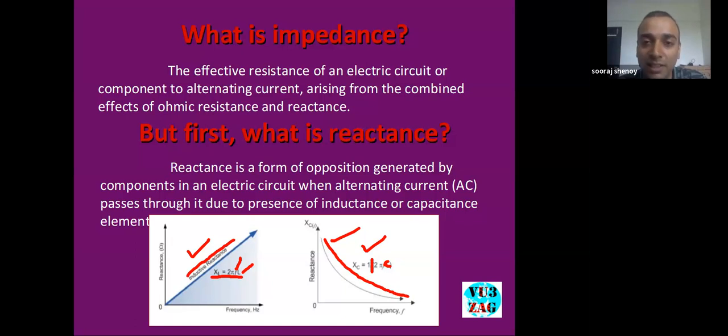As I mentioned, this is a QRP tuner and can work perfectly below 25 watts. For higher watts, the same design can be used, but the capacitor needs to be changed. At that time, we might need to use an air capacitor with high spacing in between, and vacuum capacitors can also be used. The inductor also needs to be wound on a better core. Since I am using a T52 type toroid, it's very small. For high power applications, you might need to use an air core.